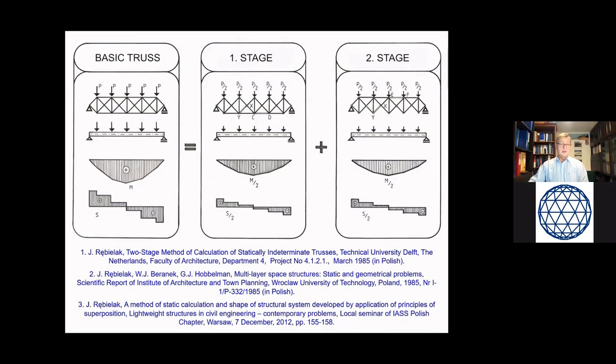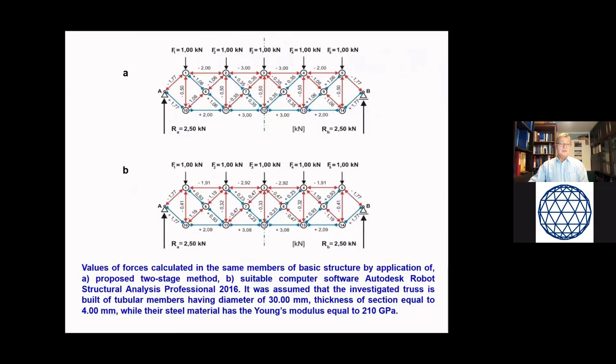It is dictated by the principle of superposition and the rules of the calculus of vectors. The differences between the force values calculated in the same truss members by the application of these two different methods are rather small. From the comparative analysis of the results obtained in both calculation methods, it follows that the two-stage method can be applied as an approximate method of calculation of statically indeterminate trusses.